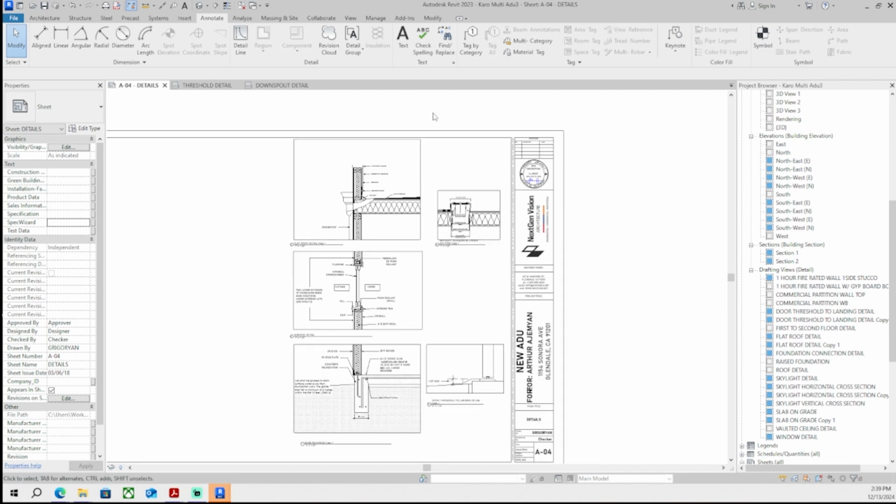When you put in or approved equal at the end of a specification, it gives the contractor some leeway, because it's not the end all be all where it has to be exactly as drawn. It's this or an approved equal. So if the site condition deviates from what's in the drawings, the contractor can do something equal to what's shown, drawn, or specified, and have that approved by the inspector without having to go back into the plan check process and waste more time.